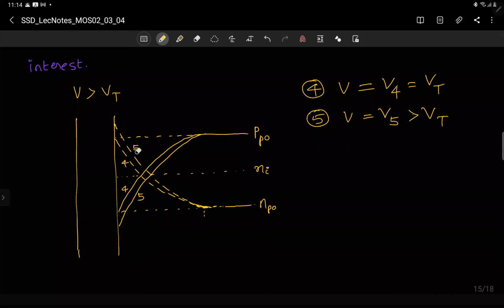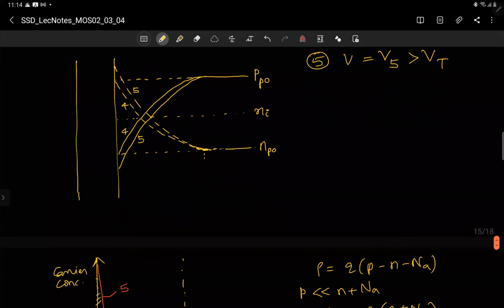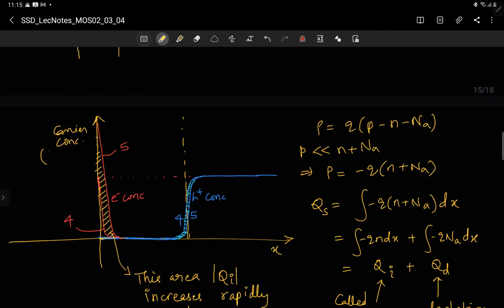If you see what is happening in terms of the charge picture, this is the carrier concentration. If I plot in linear scale, you see that the holes are depleted for a very large region. This is say xd inversion, at the onset, where the carrier concentration rises steeply in log scale.